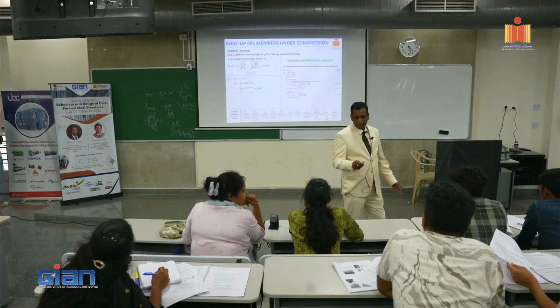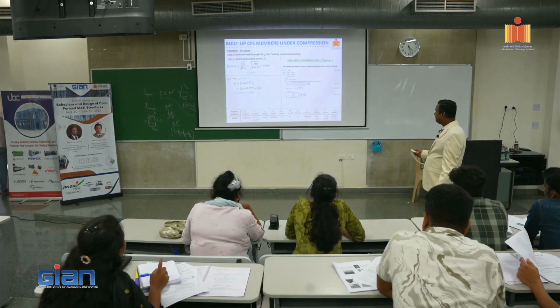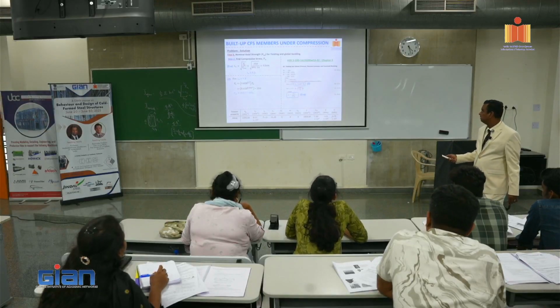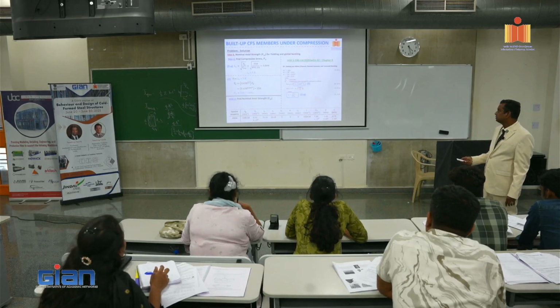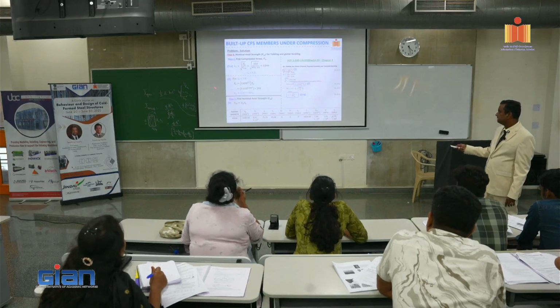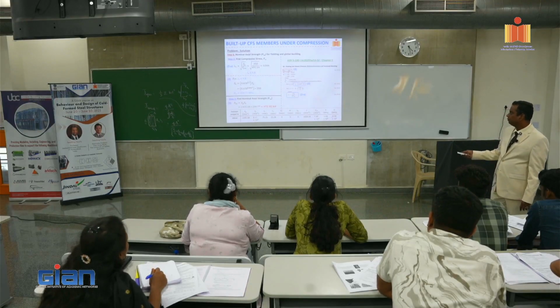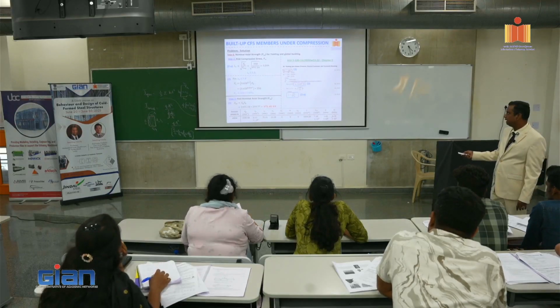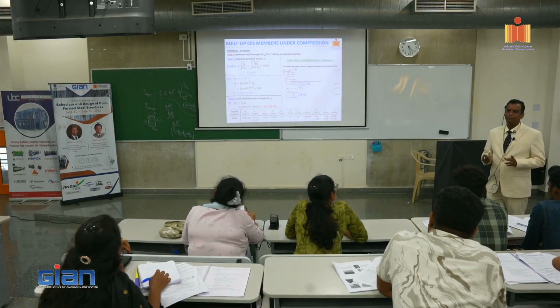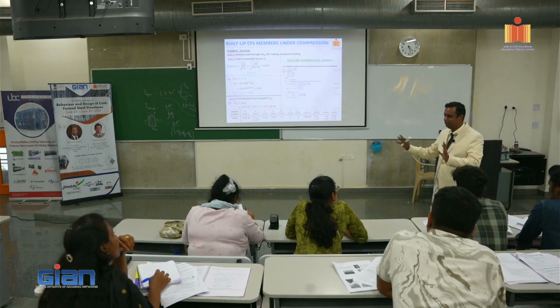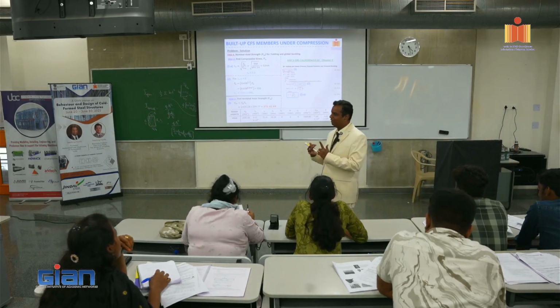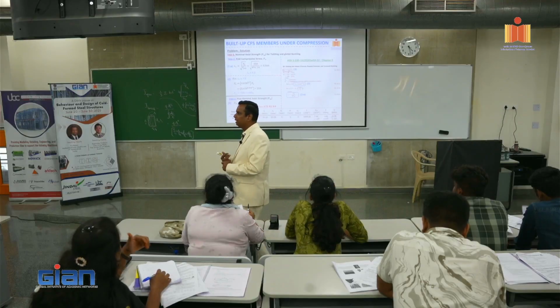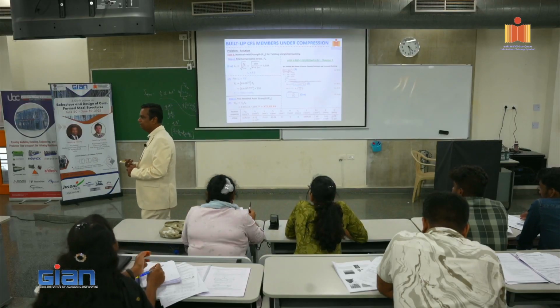Once I got Fn, I'm going to multiply with Ag. Right? So Fn into Ag, I get 1453.2 into 259.77, it is 372.82 kilonewton. So one third of the problem is done, which is I have calculated the nominal Euler buckling load.